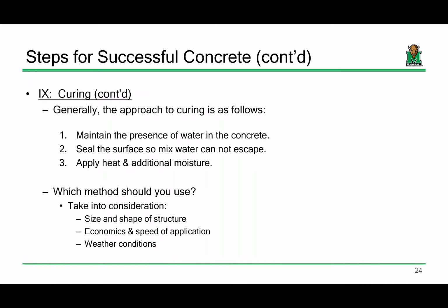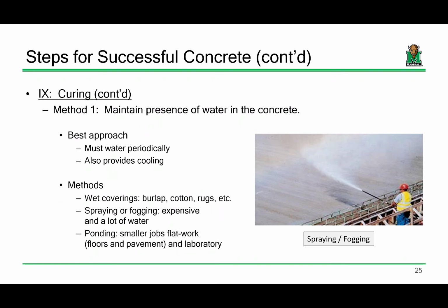What our goals are with curing is we want to try and keep the moisture that's in the concrete locked in. We want to seal any surface that is exposed to the atmosphere. And if we need to apply additional moisture or heat, we want to do that. For those of you that have been on DOH construction projects, I'm sure you've seen this done before, where that white goopy stuff is sprayed. Its goal is to lock in the moisture and ensure that you don't get a lot